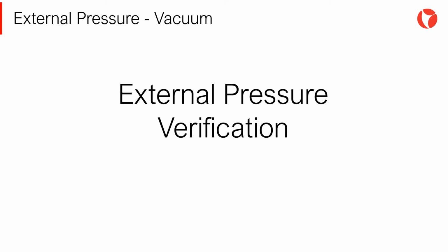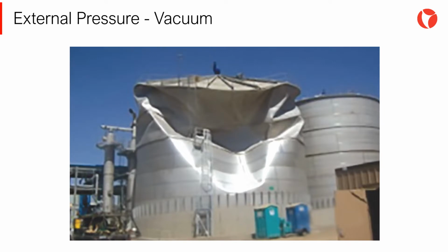The failure mechanism of a tank subjected to external pressure is different from the failure due to internal actions. Failure due to internal actions can be understood as failure of the tank due to overstress in a part of the tank, exceeding the allowable stress of the material. Meanwhile, for the case of external pressure, the tank cannot support its geometric shape anymore. Suddenly and irreversibly collapses, adopting a new configuration of smaller volume.